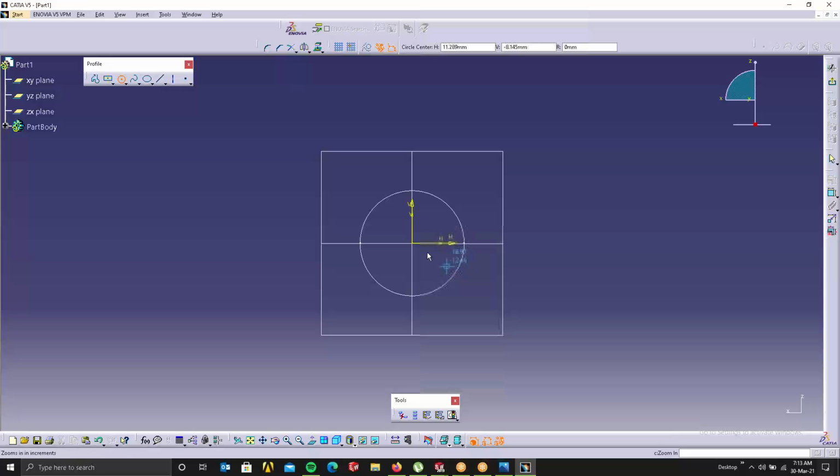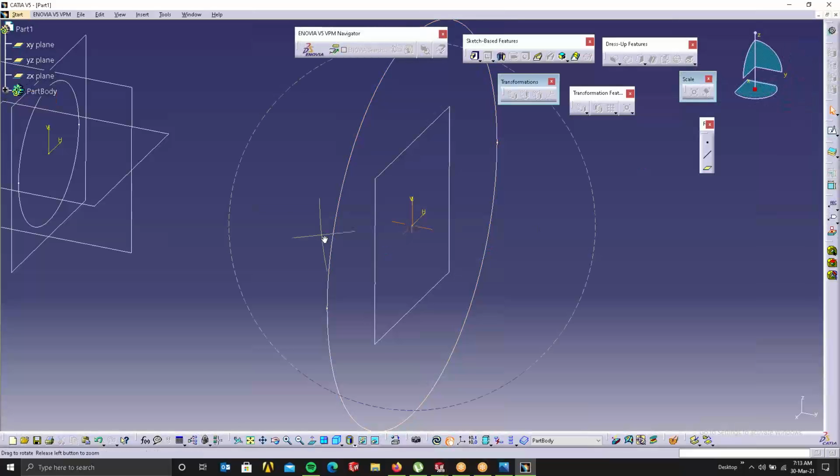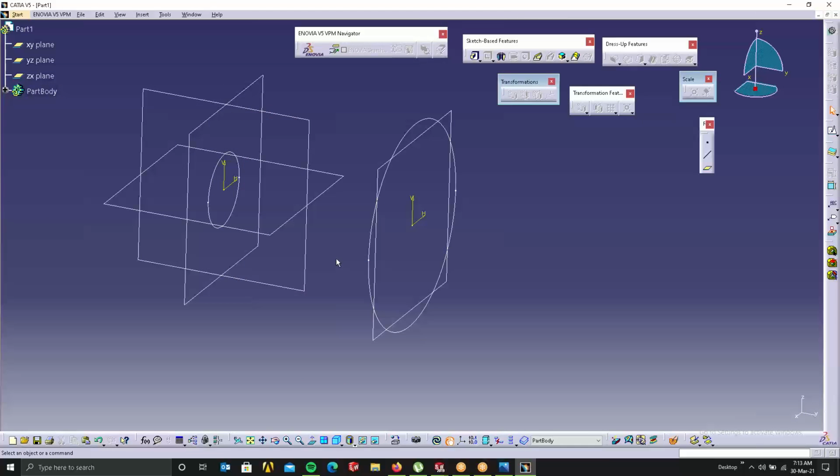So in rib and slot, what happens is the dimension is not going to change, right? The same circular profile is going to travel throughout the length. But in this multi-section solid, we have the advantage to create any dissimilar profiles and combine them. We can combine any two dissimilar figures. So here you can see one circle diameter is small, one more circle diameter is big.